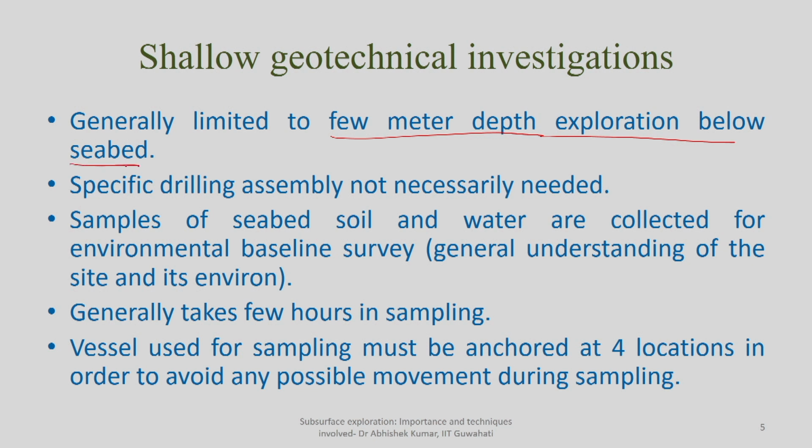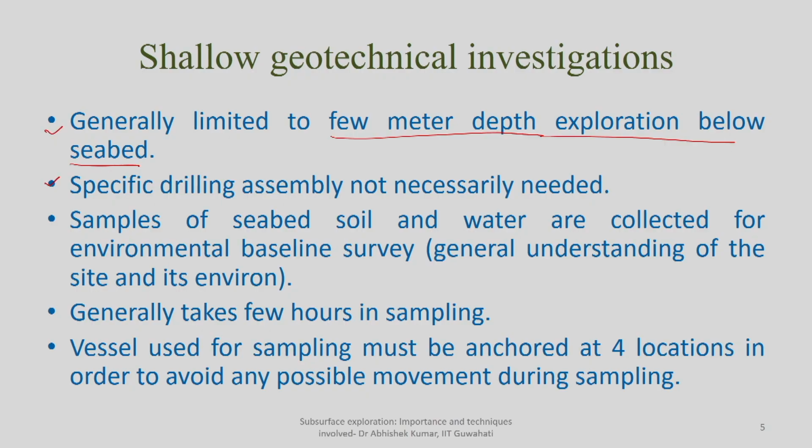In the case of exploration, whenever I give a dimension, it is with respect to the sea floor and measured downward. Specific drilling assemblies are not required here, because you are only interested in a few meters. You can use samplers specifically designed for sample collection in the offshore environment, but specific drilling is not required in this shallow investigation.